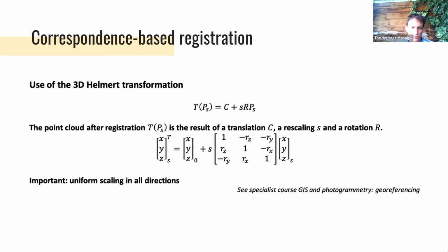Well, luckily for us, there are two very interesting things. First of all, since we are working with a laser scanner and since the distances are a priori correct, we will set this scale parameter to 1. So we will just eliminate this last parameter. And also, because we level our instrument, we have an additional constraint, namely that for all the scans, we will have our z-axis pointing upwards, so we can only rotate in our horizontal plane.